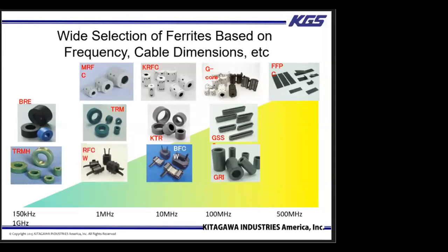In general, ferrite cores are in the single digits of dB. Usually you get a minimum of 3 dB, or as high as 10 dB. But if you need anything more than 10 dB, we usually recommend selecting shielding material, which is a cable shielding material that has better attenuation, to help combat the EMI noise.